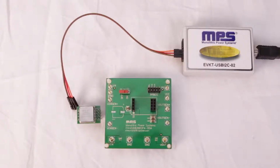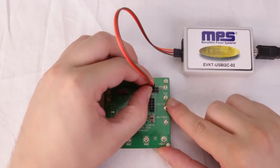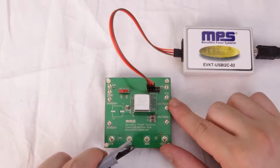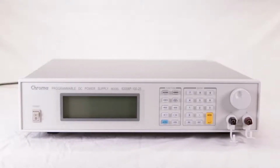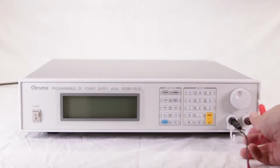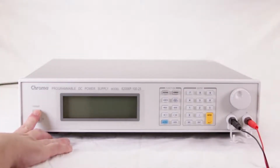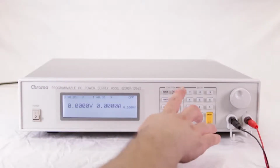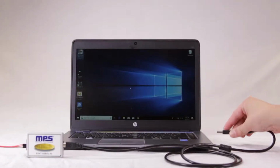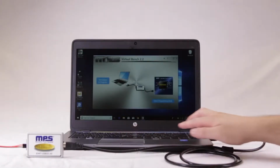To begin, connect the board to the I2C communication interface device. Plug your mEZ module into the board and connect the board to the power supply. Be sure to connect the board to the power supply using the correct voltage requirements. The voltage range for this module is 4.5 volts to 36 volts. Turn on the power supply to start up the module. We will connect with 12 volts. Finally, connect the I2C communication interface device to your computer and start up the virtual bench software.